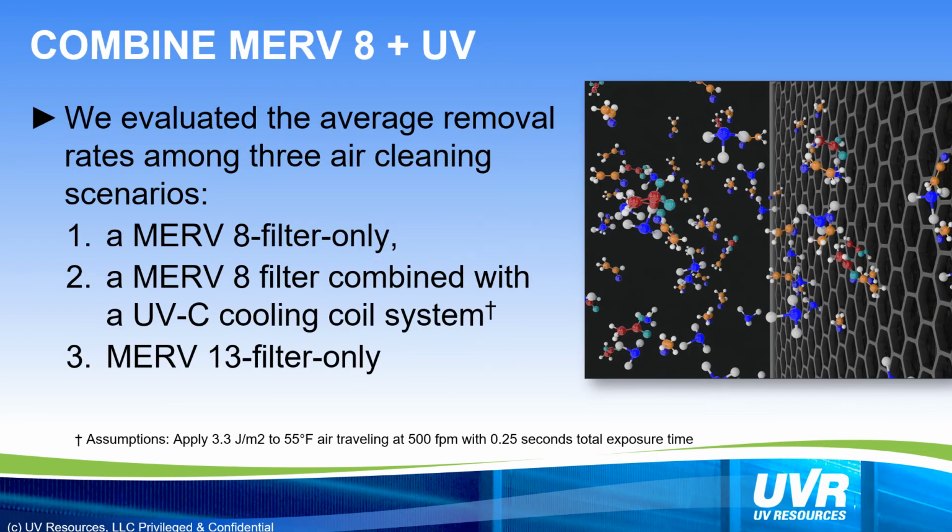In fact, the ASHRAE Epidemic Task Force endorses flexibility in meeting its standard by stating, quote, "air cleaning technologies can be combined to produce the desired MERV 13 equivalent level of air cleaning." So the Epidemic Task Force recommends that we target the pathogen removal rate equivalent of a MERV 13 filter.